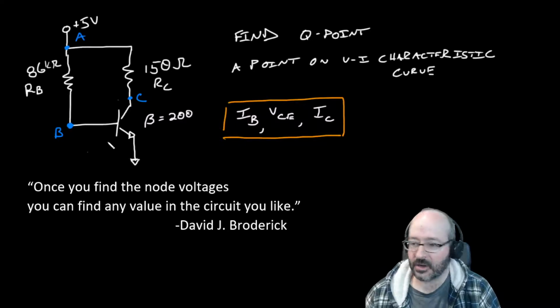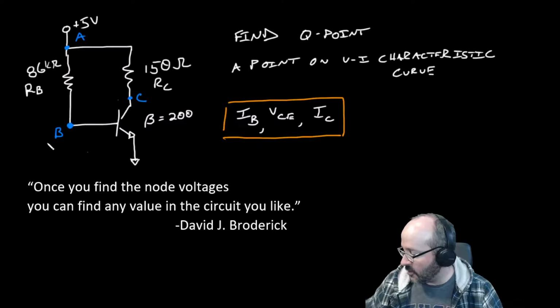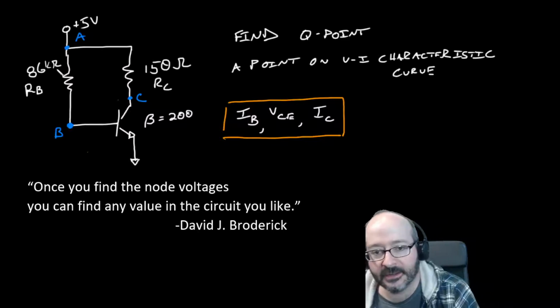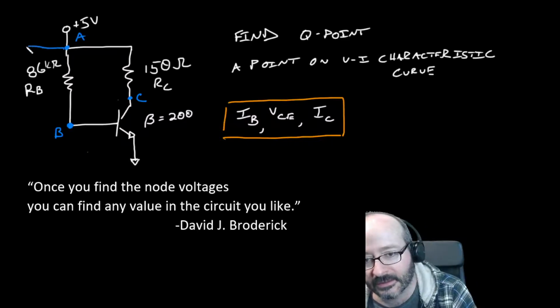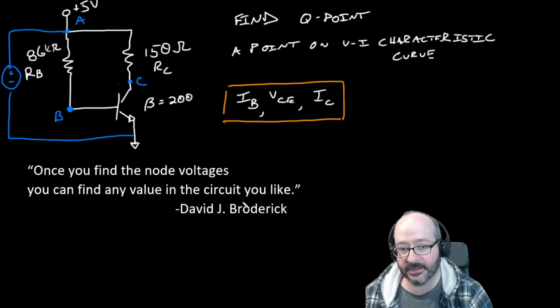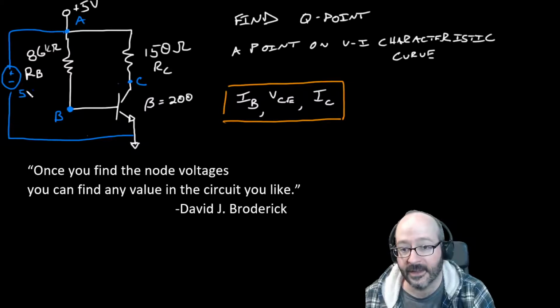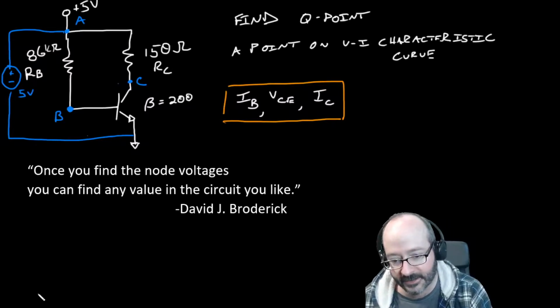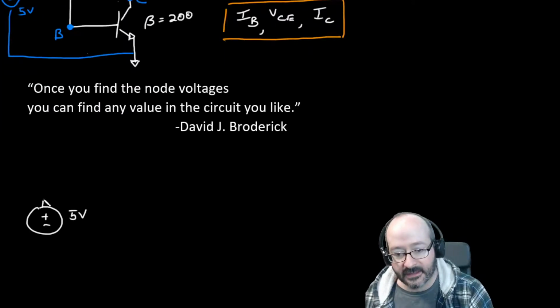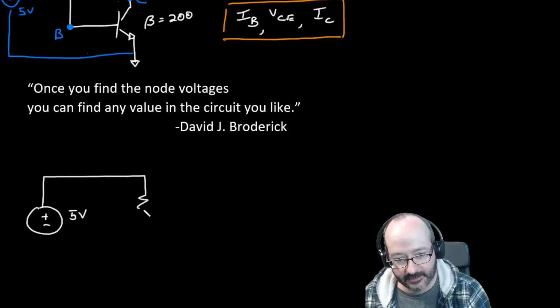So we have to redraw that circuit using the equivalent circuit. I want you to remember that there's a voltage supply out here too. When you get one of these bubbles, think about it as a voltage supply connected to ground, just like that. I'm going to start by copying that 5-volt voltage supply down here, just off the screen. I'll scroll up in a second. There are probably cleaner ways to draw this, but I want it to somewhat match what's going on.